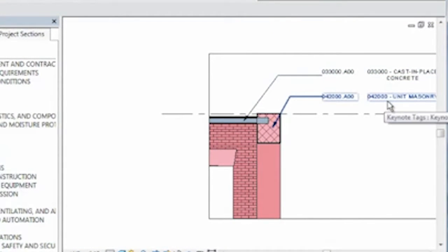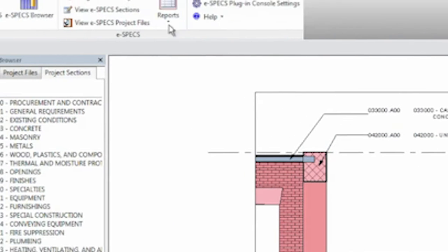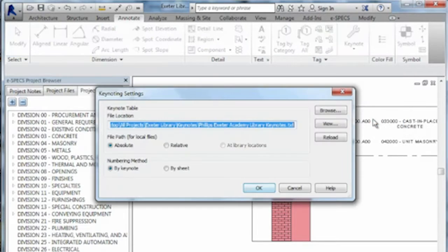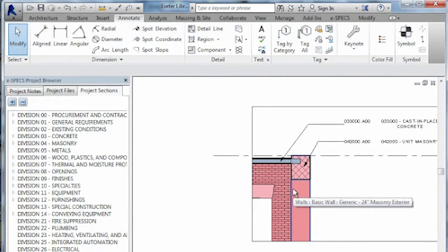Remember to point the Revit model to the correct keynote file in the Revit keynote settings. Once you click Apply, all the families and materials you set with keynotes will automatically be updated with the latest keynoting parameters filled in and ready for applying to drawing sheets.